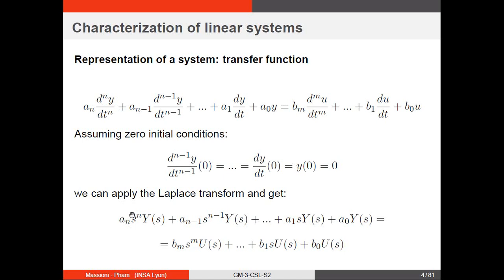You see, this is what happens on this side, and on the right hand side with u, you just get the derivatives of u becoming big U of s times s power 2, etc., s power m. So you see, the Laplace transform has transformed this equation into an algebraic equation. And what has happened here? Nothing special. It is just the same equation, the same signal, in a different reference frame. You can think of it like this, in a different reference frame.